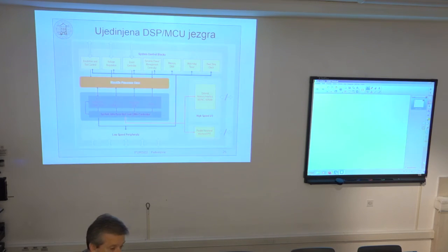You address the first address in the external memory and just say, give me sequential addresses. Okay, give me next value, give me next value, and this can be done practically at the same speed as this cache memory. So the read from memory in blocks is always more efficient than read of individual locations from random addresses.